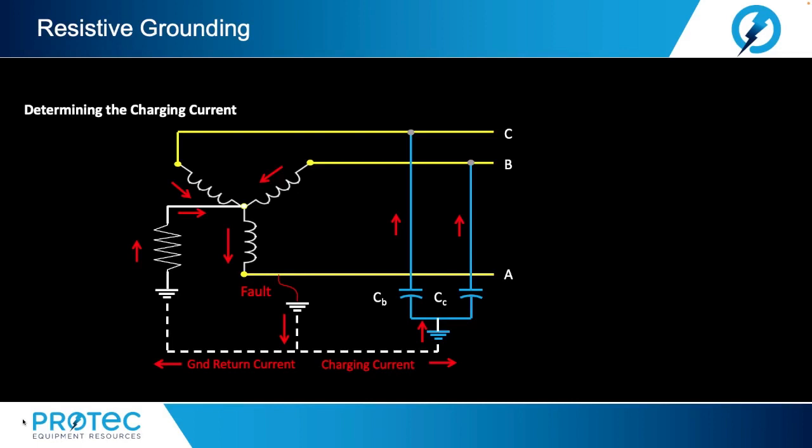It is important to note that the capacitive charging current of a system is the current that flows toward the unfaulted phases during a ground fault. This current is different from the leakage current that flows to ground from the phases during normal operation. The leakage current, typically of very small magnitude, will continuously flow through insulation.